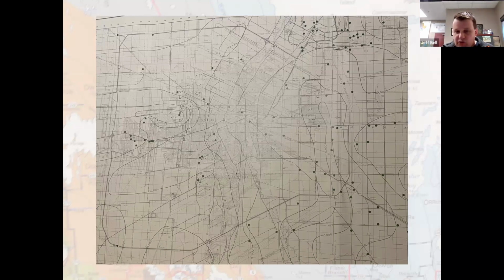And that again is mostly related to the fact that the aquifer there is fractured. If we run into a lot of fractures, then you're going to get great yields and very transmissive rock. And sometimes we don't necessarily have those conditions. So having an understanding of the transmissivity is a really important thing, particularly when you're working in Winnipeg.